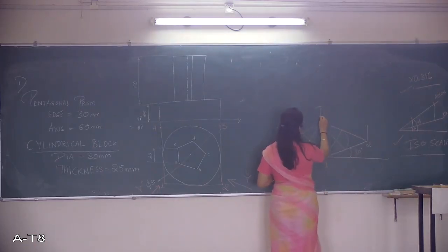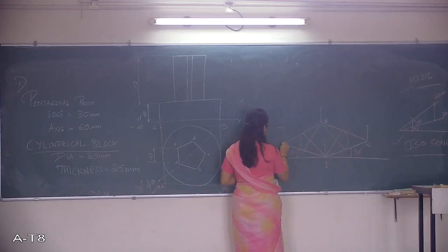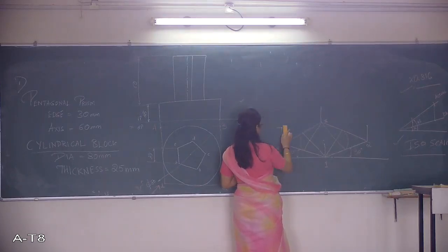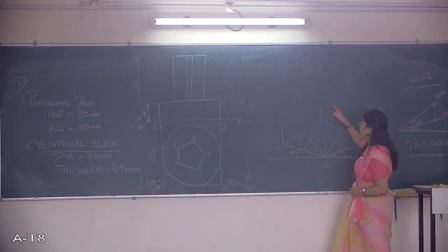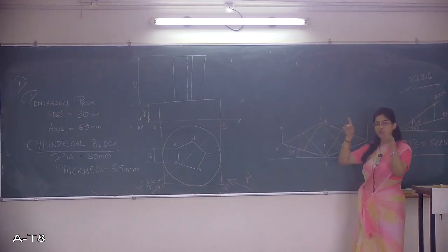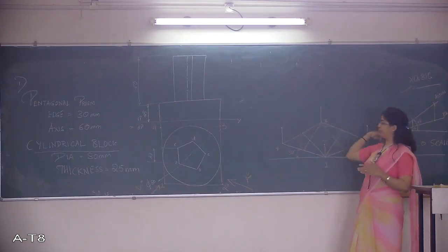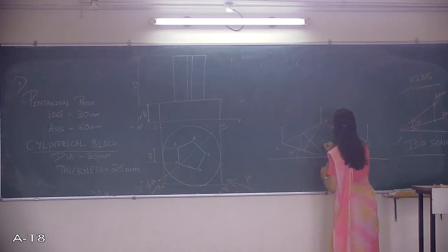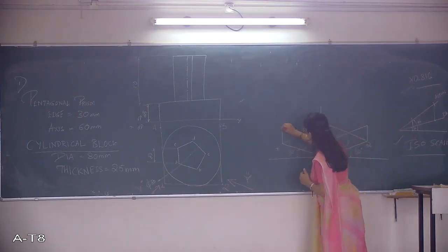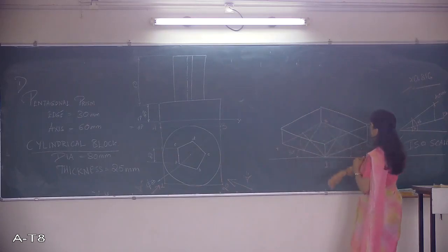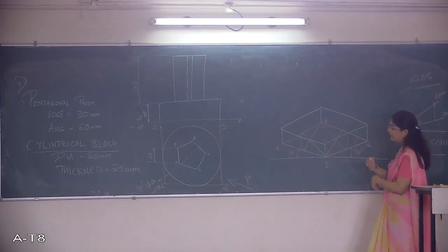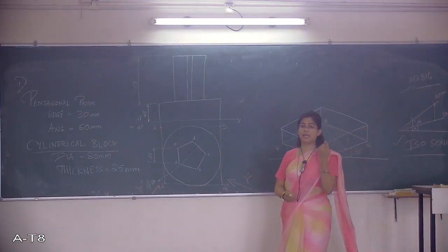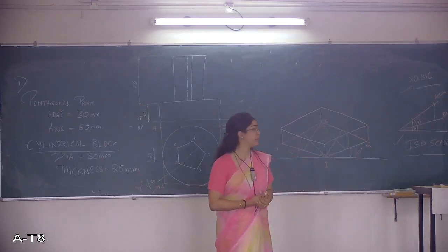Likewise, I'll see where this is. So now, if you see, I have got 4 new points to mark, 1, 2, 3, 4, the square for the top face of the cylinder. So next, I can just join these. This is how I have just joined these. Once I join them, again I have to repeat everything in order to get the ellipse for the top face of the cylinder.